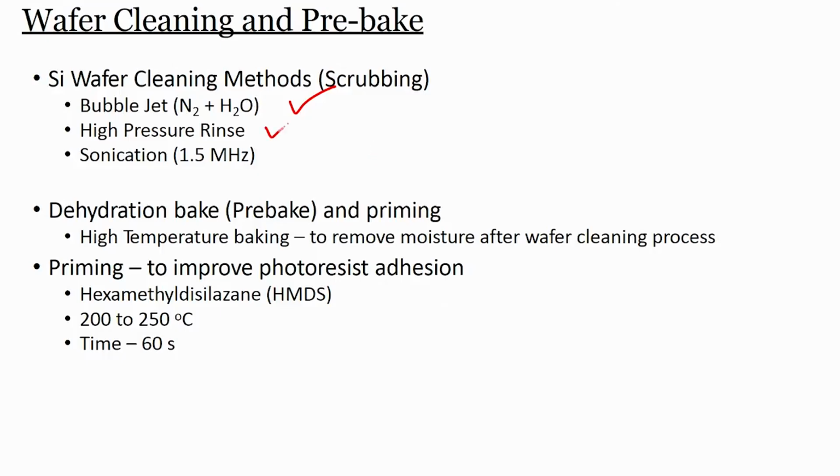Second, with high pressure you can rinse the wafer. Third, you can use a sonicator and clean the wafer. The sonicator is used at 1.5 megahertz, and these are the cleaning techniques for silicon wafer.